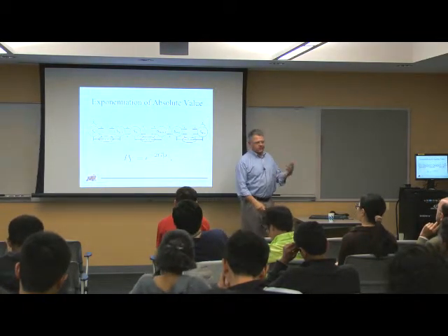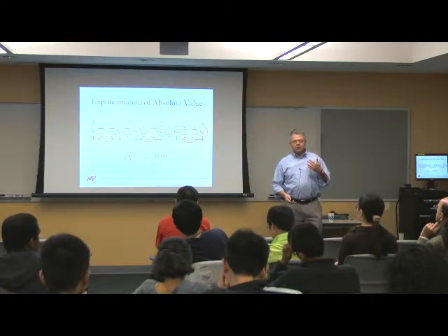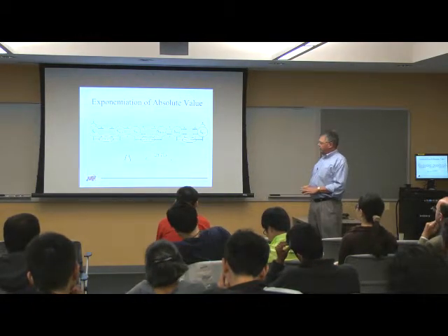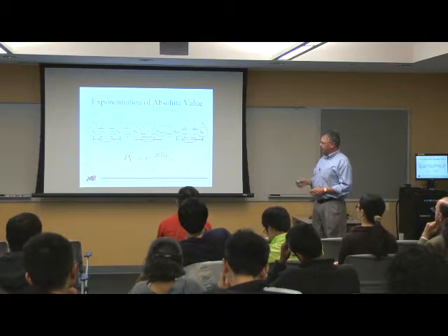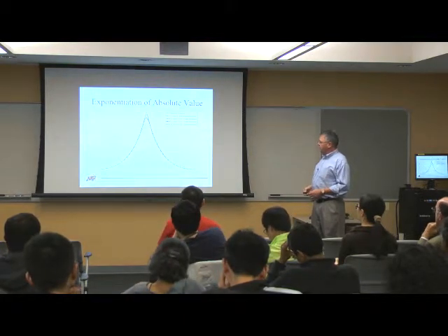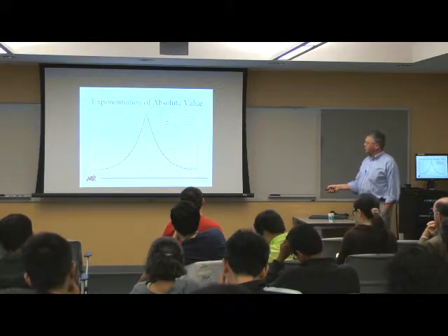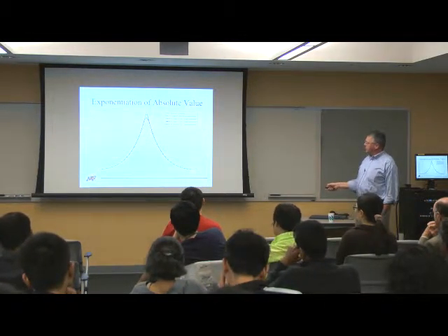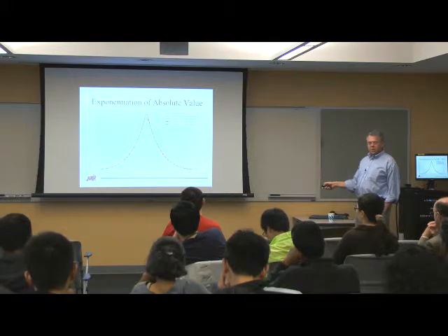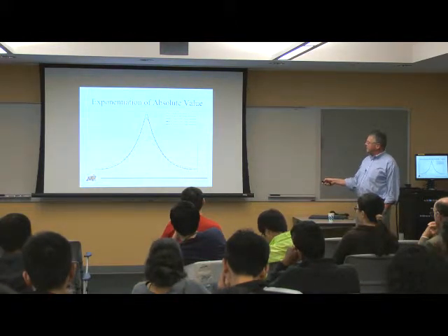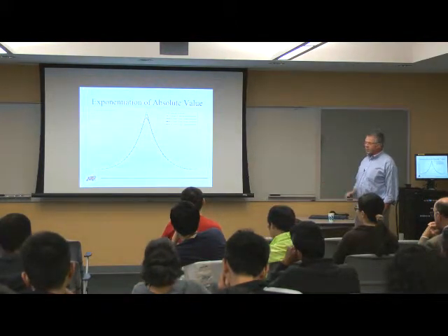That parameter g turns out to have some impact on the noise that this circuit generates. But for now, just think of it as a constant. If I do that, the ideal version of this function is this gray line, which peaks in the middle. If I have an 8-state implementation, I get this yellow line, then 16 states, 32, 64 states.